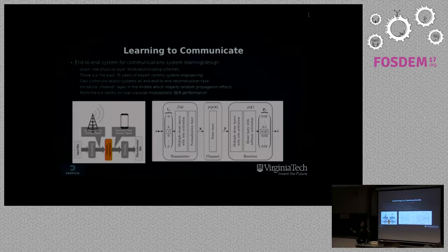That's pretty much what an autoencoder does in machine learning. It takes some input, goes through a couple different representations of it, and tries to reconstruct the input. If we cast the basic communications problem as an autoencoder, we take some input, form some new encoding of those input bits, and go through some channel impairment, which we don't control. This is defined by a wireless environment. And then we go through this decoder representation that transforms the samples we receive back into bits.